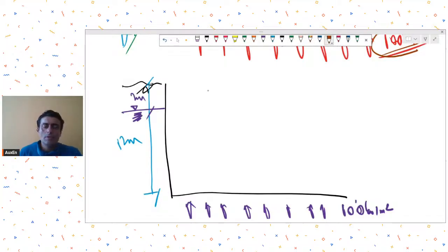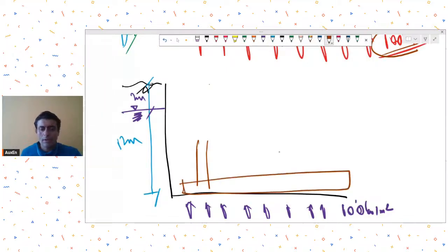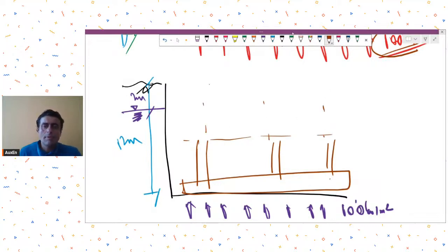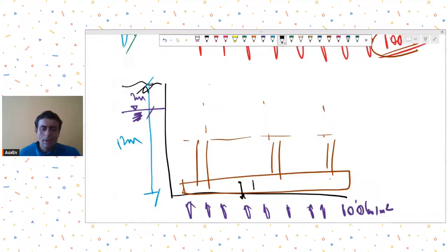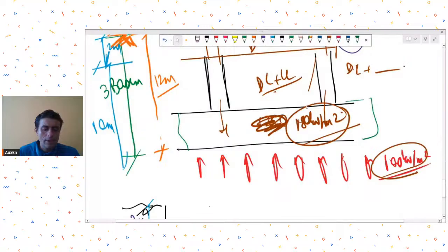The real problem is not after building construction, but when, let's say, you have only made one basement. So the raft has been provided, the other levels are ongoing, construction is ongoing. Now this is a problem. Why? Because at this stage, when you have not constructed all the floors, the bearing pressure below the soil is significantly lesser than the eventual value. You're getting this point? After construction, the water table was not a problem because the dead load bearing pressure itself was significantly higher than the uplift pressure due to the water table. So that was not a problem.